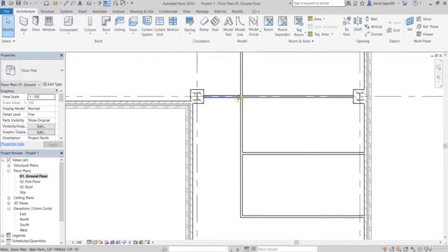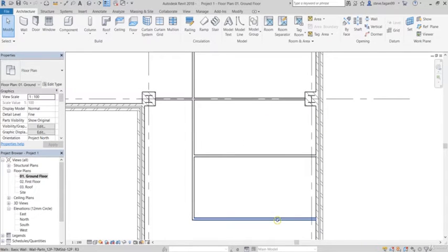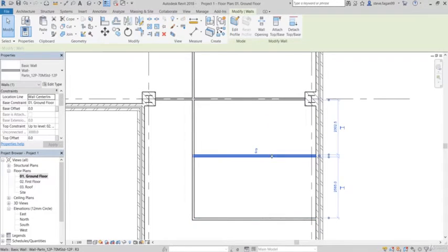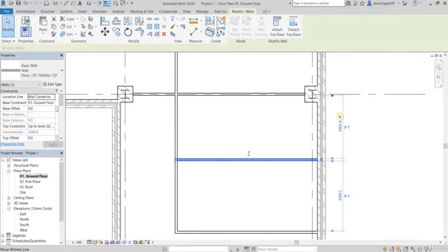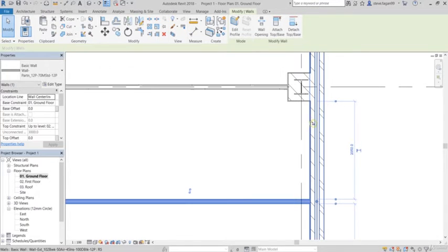So this wall here is at the center point, same here. And these walls here are 2000 down. So if I select my middle wall, you can see my temporary dimension is 2302.5. If your temporary dimension is snapping to the column like so, we can adjust its position. With that blue grip, I'll click, drag and move it up to the face of the plasterboard and let go. Now I can change the text to 2000.